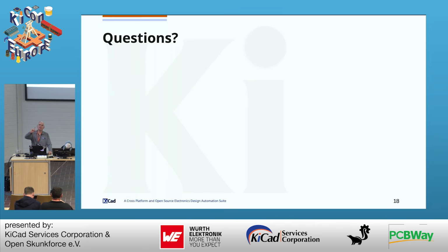Because remember, a symbol, the graphical symbol, the pins, that's really only part of the symbol, right? That part isn't variant. It's all the fields with the exception of the reference field. And you also can't use a different unit number. I forgot that one in there. I mean, that would change the design. Okay, thanks.